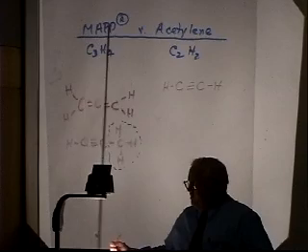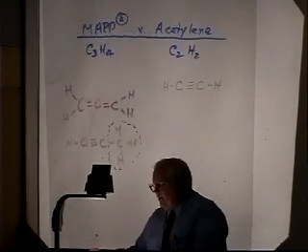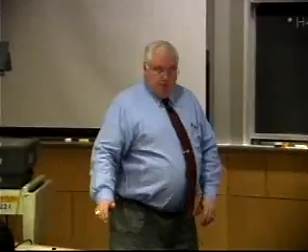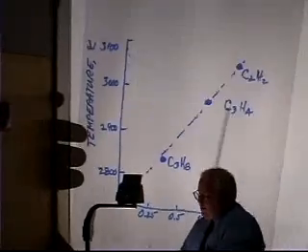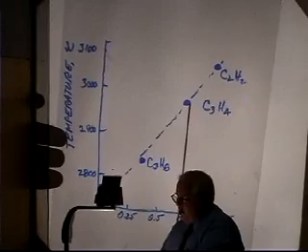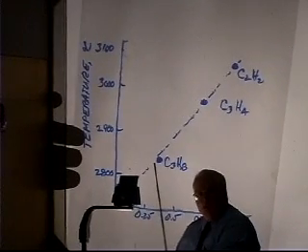So methylacetylene propadiene is actually a registered trademark called MAP gas, and we'll talk later about why it's a desirable type of gas. But because it has, going back to this plot, a higher carbon to hydrogen ratio, it has a higher burning temperature by almost a couple hundred degrees over propane. So we'll now do the demonstration.